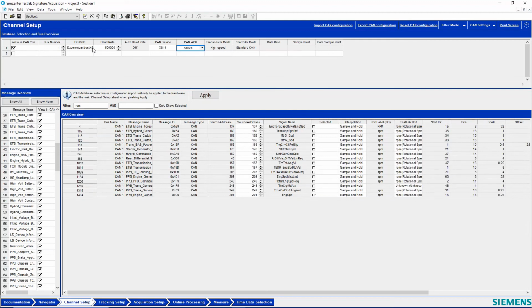And if you've selected the right OBD file, then you will be able to get these signals. It operates exactly the same as CAN. It has a limited number of signals. One of the things that is handy, I'll go back to the slides and show this, is we have a little setting here called sample and hold versus linear. And you can set linear or sample and hold on these things. Because there's a slower update rate on these OBD2 signals, it's sometimes nice to use this linear.